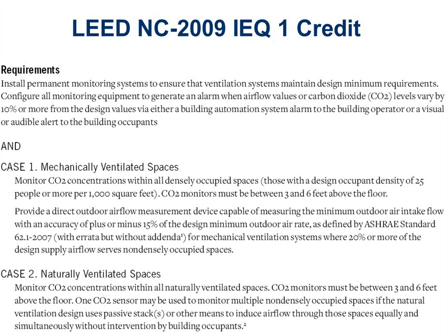What Andy's asking, there are two different things that could happen. On a constant volume system, like with a regular rooftop or air handler, with one duct system, constant speed fans, no zone dampers, and one CO2 sensor on the wall, it's pretty easy to keep it in the target range of 1,000 to 1,100 parts per million, 1,200 parts per million. If you see it lower in those spaces, it's one of multiple scenarios. One, it's an economizer day outside, and I'm trying to get free cooling. Great.